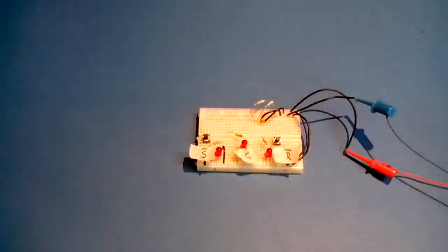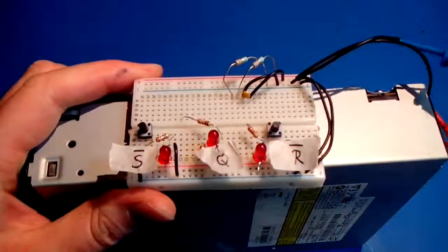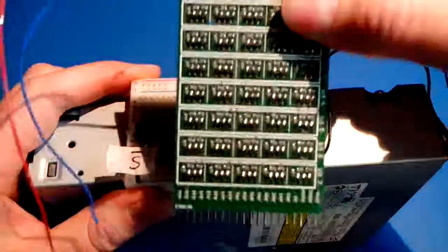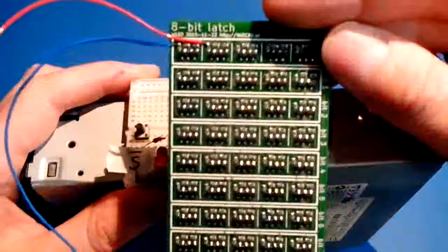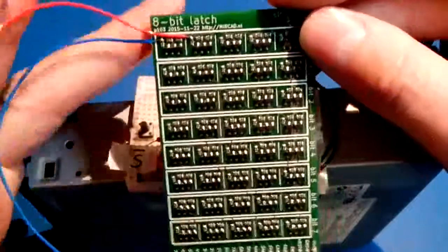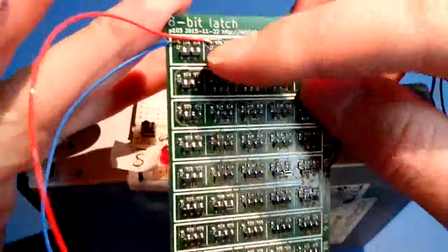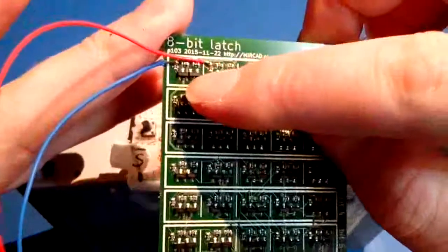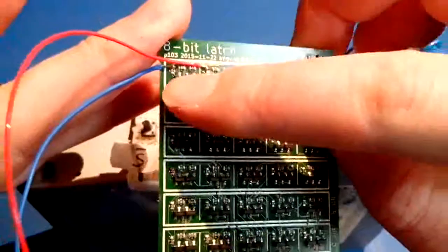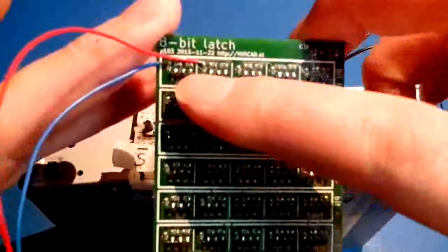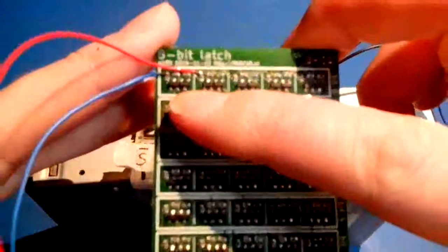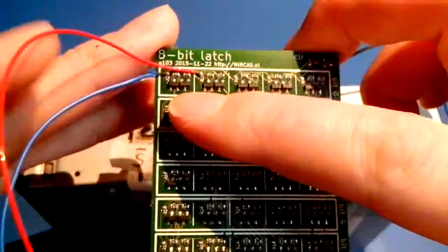So let's do that. For this I use the 8-bit latch module, also shown in another video. It has a number of NAND gates on it. For example, this topmost block in this topmost cell is a NAND gate, and the one next to it is also a NAND gate. And these two NAND gates within this module form a set reset latch, where the leftmost NAND gate, so that's the leftmost cell, the leftmost two transistors form the set